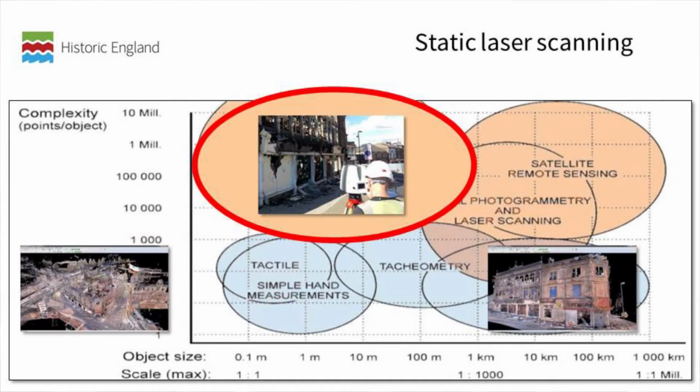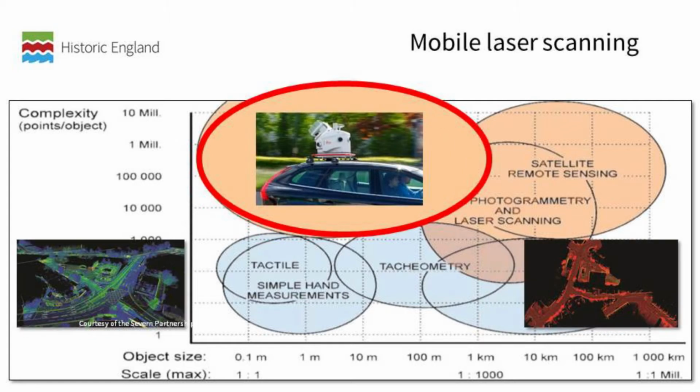What I'm more usually involved in is laser scanning of buildings. So scanners are normally mounted on a tripod, and you're looking to measure to a resolution between the points that you're measuring of sub-centimeter, so a number of millimeters generally. For larger areas, there's now systems that can be mounted on vehicles, so cars, on the railway and so on, which again collect millions of points, but basically the sensor's being driven around the area of interest. It's normally used for things like city mapping.